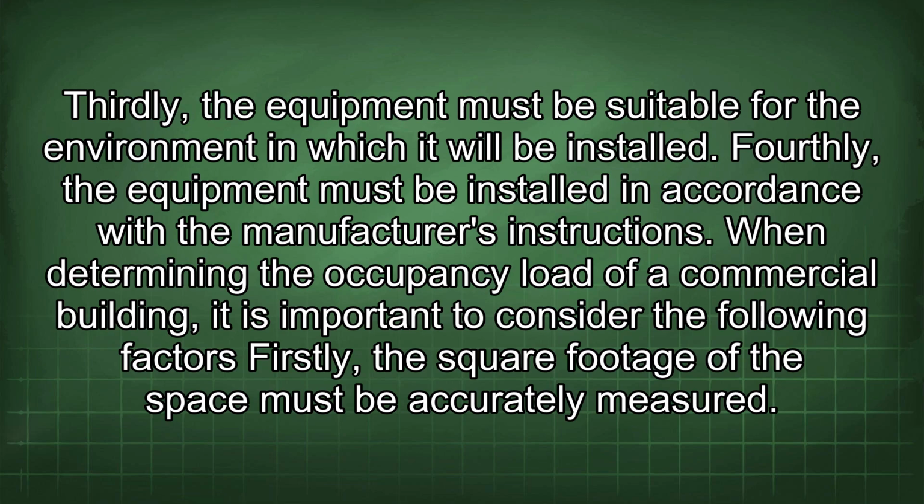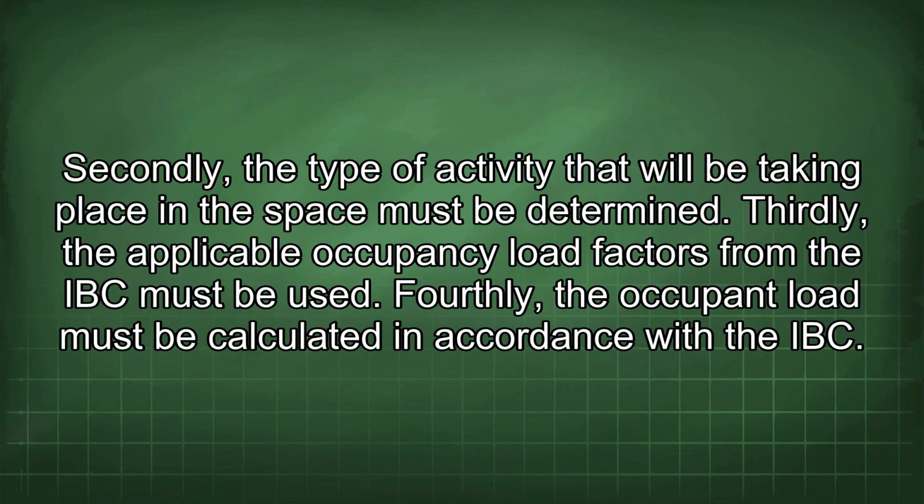When determining the occupancy load of a commercial building, it is important to consider the following factors. Firstly, the square footage of the space must be accurately measured. Secondly, the type of activity that will be taking place in the space must be determined. Thirdly, the applicable occupancy load factors from the IBC must be used. Fourthly, the occupant load must be calculated in accordance with the IBC.